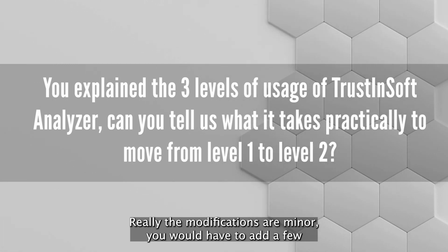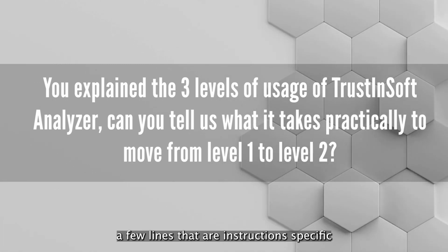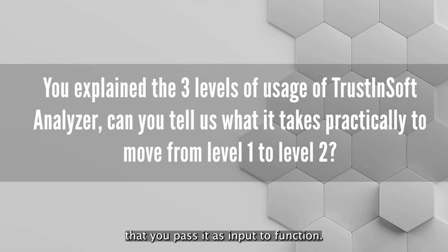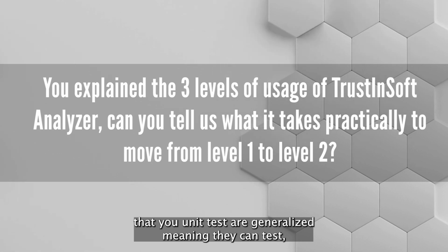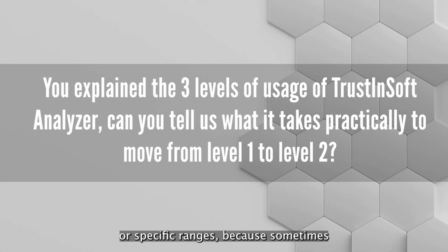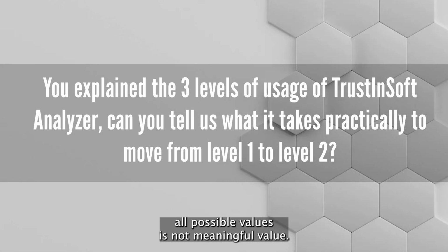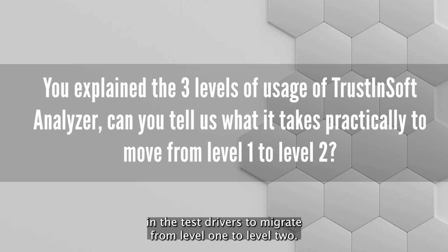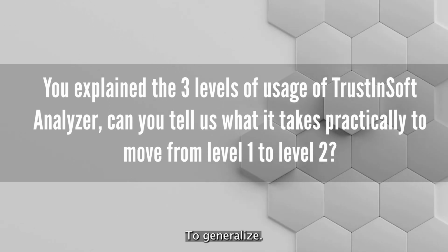Really, the modifications are minor. You will have to add a few lines that are instructions specific to the TrustInSoft Analyzer to specify that all the parameters that you pass as input to the functions that you unit test are generalized, meaning they can take all the possible values in their range of values, or a specific range, because sometimes all possible values is not a meaningful value. So it's only a few lines to be added in the test drivers to migrate from level 1 to level 2, to generalize.